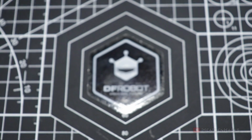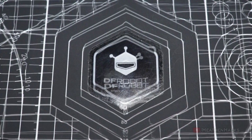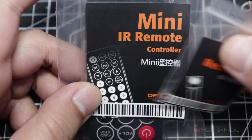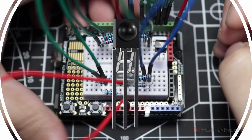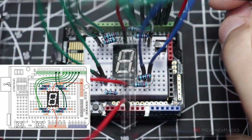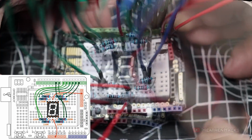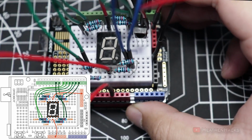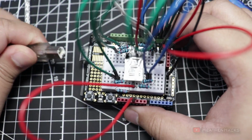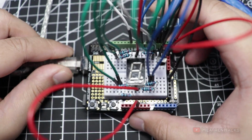Okay, this time we're going to need two more components: the IR remote control, of course, and an IR receiver. Let's connect the IR receiver right here. Remember that the flat side should be at the back. Connect the right leg to 5 volts, middle leg to ground, and lastly the left leg to DFRduino's digital pin number 11. Alrighty then, let's plug in our board to the computer.